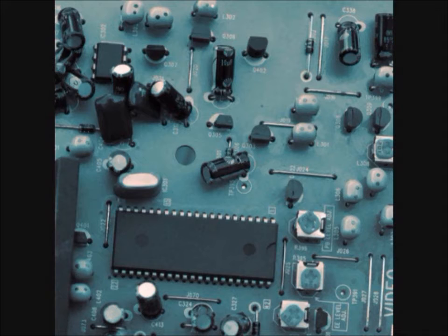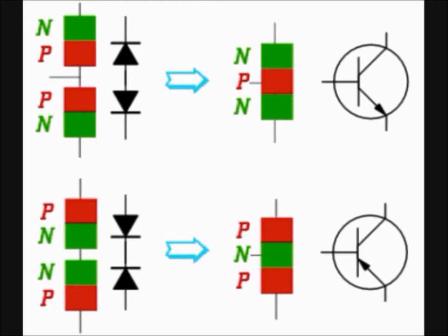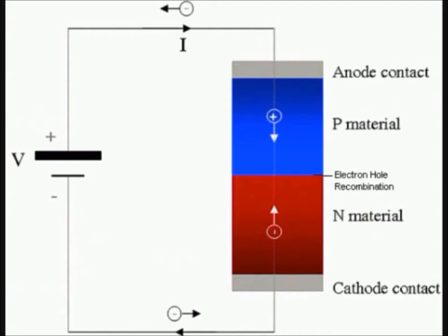Solid-state devices included diodes, which also rectified current, but used much more hardy semiconductor layers to do so, and transistors, which amplified current. To illustrate, the semiconductor diode is a device that, like a valve, rectifies current. It only requires 1 P-type and 1 N-type semiconductor to work. When the current flows from the P-type to N-type semiconductor, the electrons and holes move towards the center of the diode and cancel each other out in an electron-hole recombination.